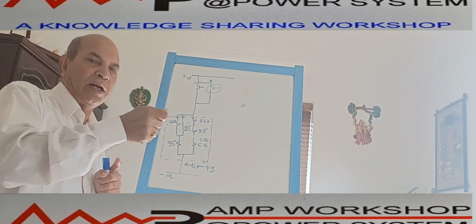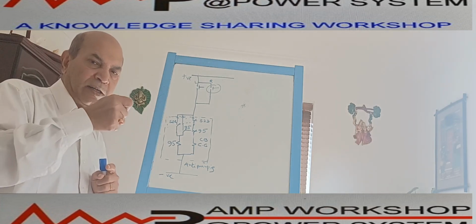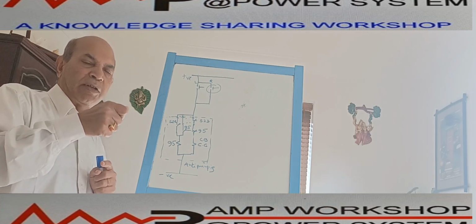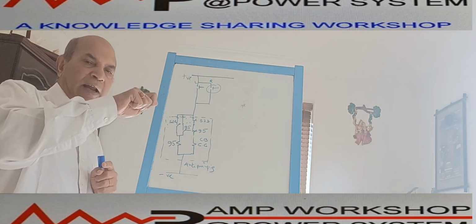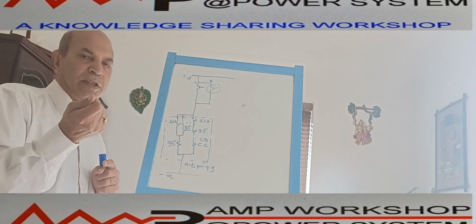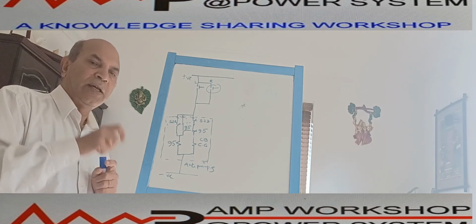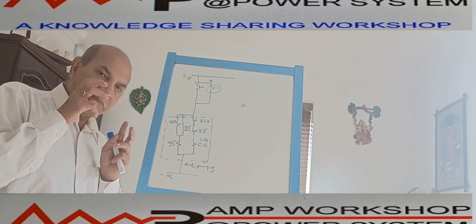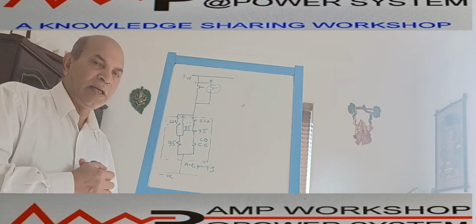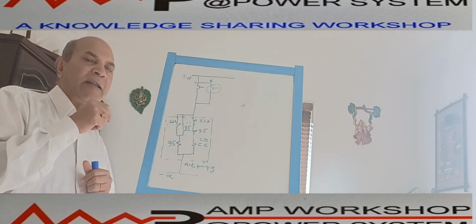Even if you try to be smart, and you are thinking, if I keep the switch on in advance and hold it after crossing the 12 o'clock, then my operation will be all right, that will not happen, and the breaker will not allow this, because that safety protocol is already inbuilt within the circuit breaker, and that is called the anti-pumping circuit.